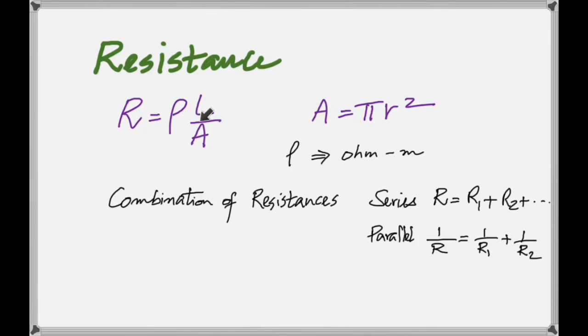Now, this is where I've asked questions like, if you stretch a conductor to twice its original length, what happens to its resistivity? It remains the same, because resistivity depends on the material, right? So you've got to be careful. Once again, I'm telling you, don't be mathematical alone. You have to think. So just don't go, hey, I have all the formulas, I'm going to get everything. No, you're going to be tricked. So if you only look at the formula and you're not thinking, you will say, oh, the length is doubled, the resistivity should become half or something like that. But resistivity is a constant.